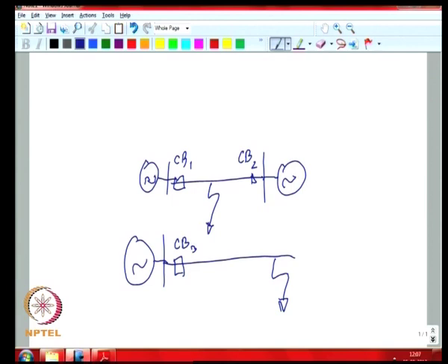And also as you proceed along this particular feeder, the ratings reduce as you go further down the feeder, as the loads are typically connected uniformly across the length of the feeder. So, the rating of something which is much closer over here would be higher, the ratings that are towards the middle of the feeder would be lower. So, you have simplicity and cost reduction in a number of ways.